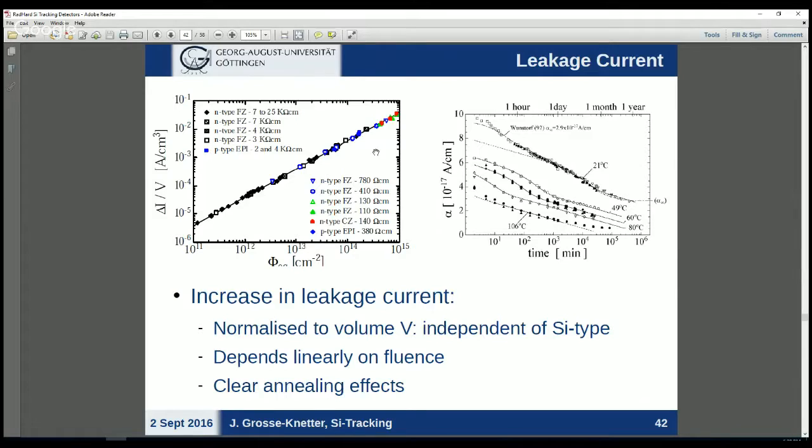That's an electronics trick that we actually apply. We benefit to some extent from what I mentioned earlier on. We have small electrodes, so the effect per electrode is small because the volume beneath is small. The effect, of course, grows with the volume. So the pixel detector actually is intrinsically better in terms of surviving the increase in leakage current. That's a very good part.